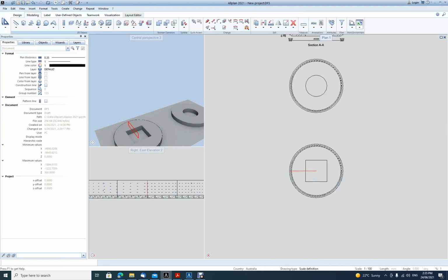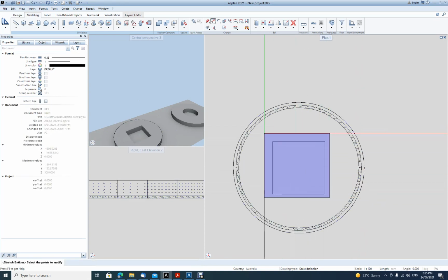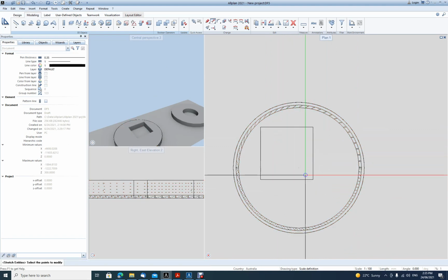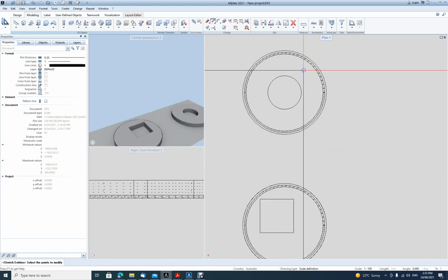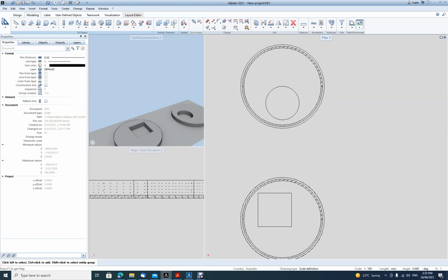The 3D line which I used for a section can then be moved away, and the openings can be moved around if you maybe want to have it on the other side. With these 3D models, we are now ready to create the sections and follow with the reinforcements in the next lesson. Thank you.